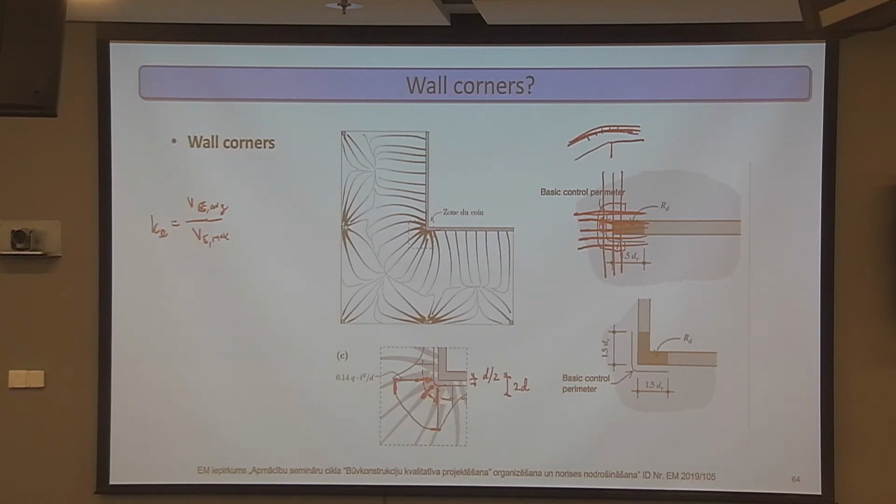It's the same thing that we talked about in the first half, that the moment field and the shear field are linked. So if we put lots of flexural reinforcement somewhere, it will also attract a lot of shear force. In cases like this, it's like a self-fulfilling prophecy: if we are afraid of this corner and we put a lot of reinforcement there, then we do attract large shear forces and we can attract trouble in this corner.